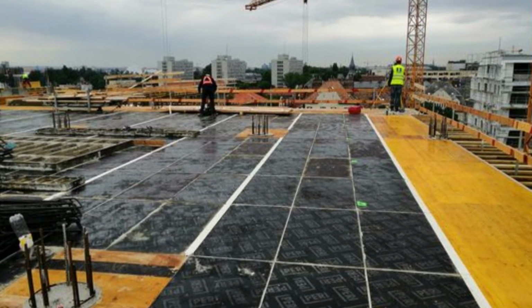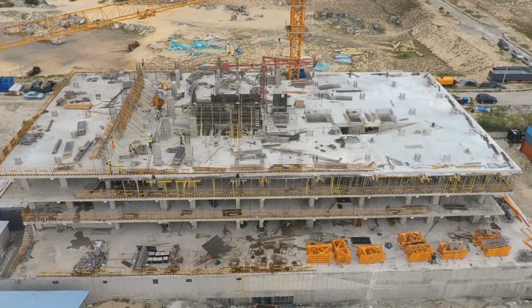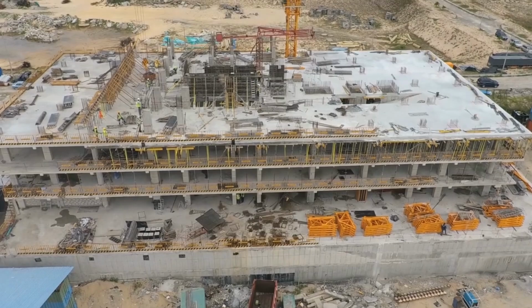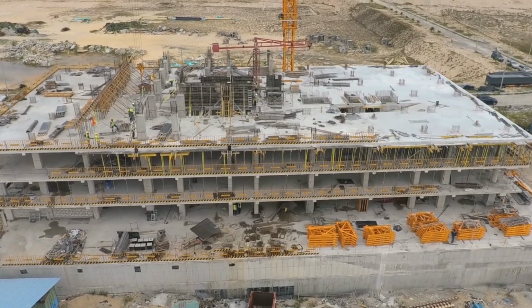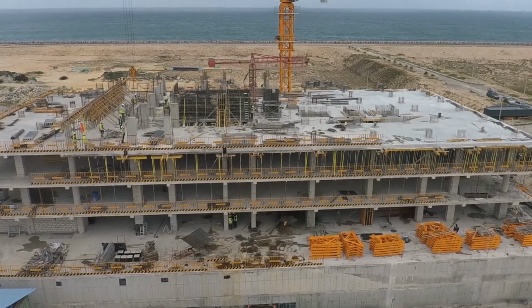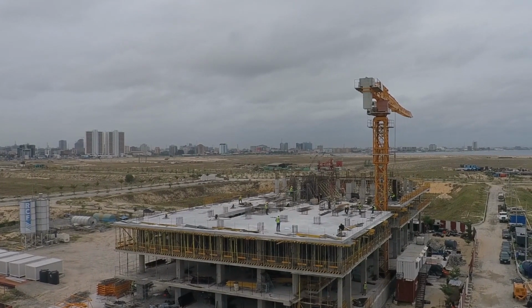All horizontal and vertical formwork joints on the exposed surface must be staggered in order for the joint lines to be visible. The size of such panels must be approved by the engineer in charge before they are used in the construction of the works if the contractor proposes to make up the formwork from standard-sized manufactured formwork panels.